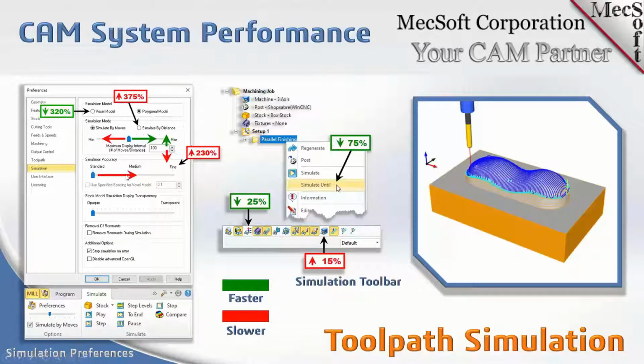On the left, you see the CAM preferences dialog. We're looking at the simulation tab. Now, these top two areas, simulation model and simulation mode. The mode correlates to, if you look at your simulate tab down below here, you have a checkbox for simulate by moves. So this correlates to the simulation mode. But let's talk about the simulation model.